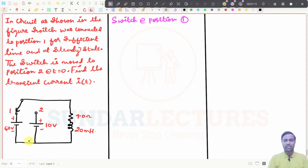We have seen these kinds of things, right? If this switch is connected to this voltage and it is left for a sufficient period of time, then the current will be E by R. That is what we have seen: i(infinity) will be E by R in the RL circuit. So I will take that as i(0), because the switch is going to connect to position number 2. So i(0) will be E by R.